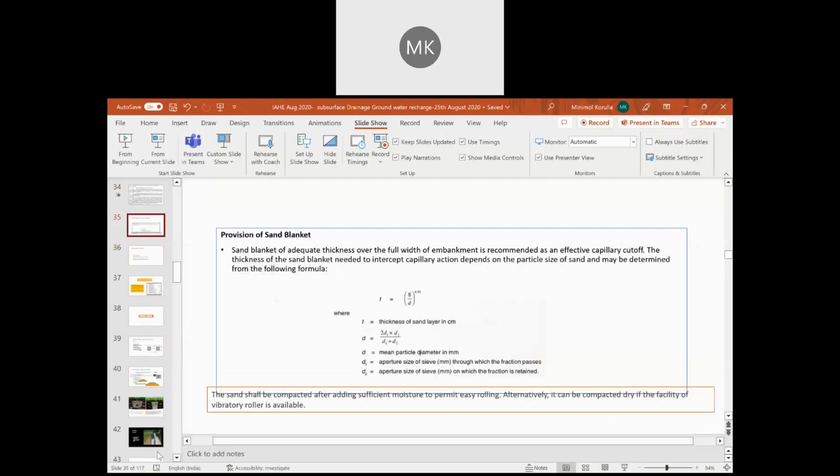Where a 600 mm, sometimes more than that and sometimes less than that, but on average a 600 mm aggregate layer, can be replaced by a few microns or a few millimeters of drainage geocomposite, which is enormously saving your space consumption. And this is especially significant where space is not there, like on a hill road. If we want a little more space for the aggregate drain, that means you have to cut the hill or extend into the valley, which has a very high cost.